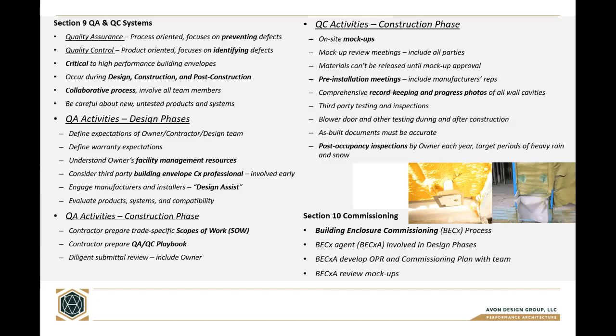The building envelope commissioning process starts during design, but really takes place during construction, where you start to have mock-ups of the various materials and how they come together, as well as having comprehensive meetings with all the people involved, from the manufacturers' reps and the contractors, as well as architects and engineers, and having comprehensive record keeping and progress photos of all of the activities as they're taking place.